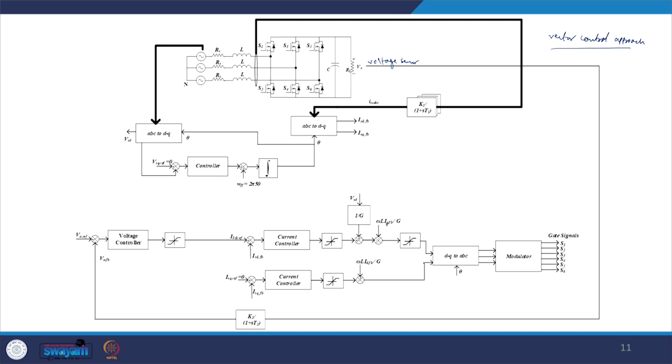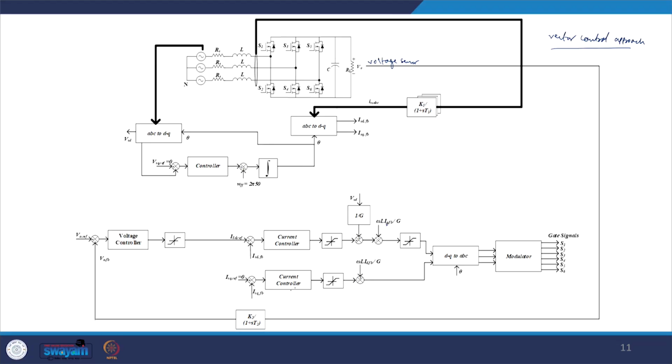That is when we are ensuring that the IS space vector is aligned along the supply voltage space vector, and that is when we can say that we are achieving balanced 3-phase operation with unity power factor current drawn from the source. And then we will have our current controller. We know how to design our current control parameters, limit, and then finally one feed forward term to negate the cross coupling effect, which is omega L ISD feedback by G, which we have already derived in our DQ axis model.